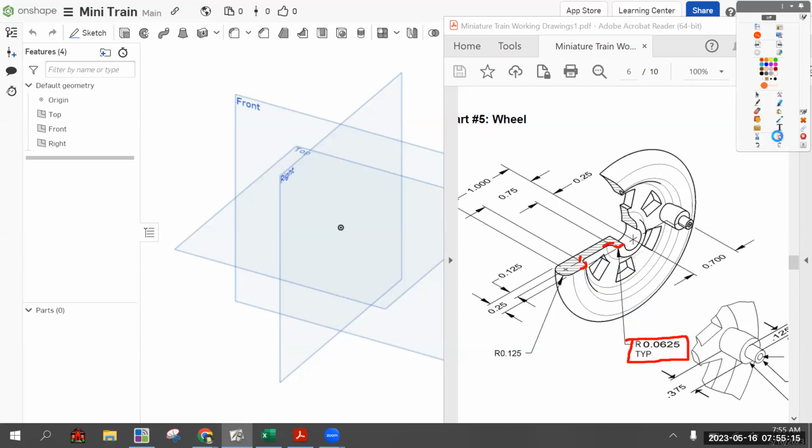There's 2 ways to do it. One is to make it part of the sketch where we have one there, one there, one there, and one there, and then do the revolve. The way we're going to do it is ignore those and just keep it squared off and do the fillet as a part feature, where once there's material, it'll smooth off, because when you do it as a sketch, it gets kind of funky. The revolve doesn't always like it.